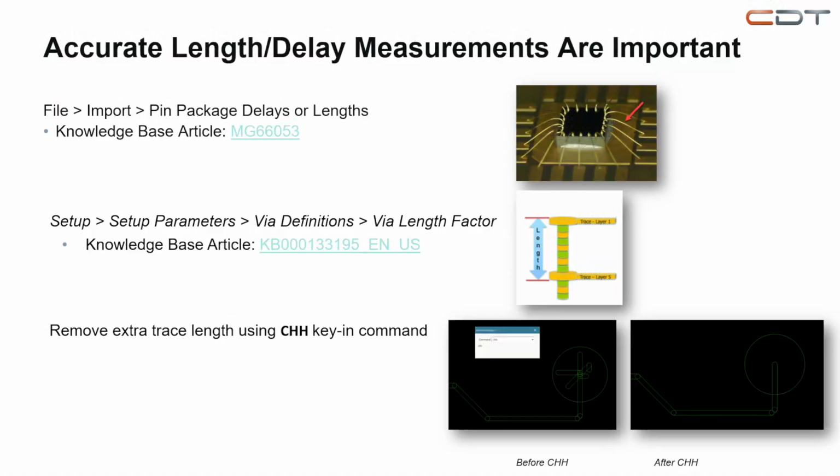The first way to do this is to make sure that you are importing the pin package delays or lengths. We have knowledge-base articles on the support center that go into the step-by-step process in more detail. But essentially, this is information you get from your manufacturer, and then you put it into a file in a specific format and import that in Constraint Manager.